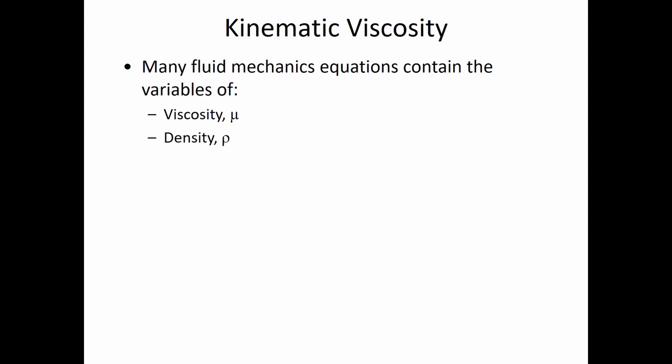There is one other phrase that you need to be aware of. I already told you that absolute viscosity is the same thing as dynamic viscosity, and sometimes we just say viscosity. Those three things, they're equal. Kinematic viscosity is different. Kinematic viscosity is used sometimes because a lot of formulas have both density and viscosity in